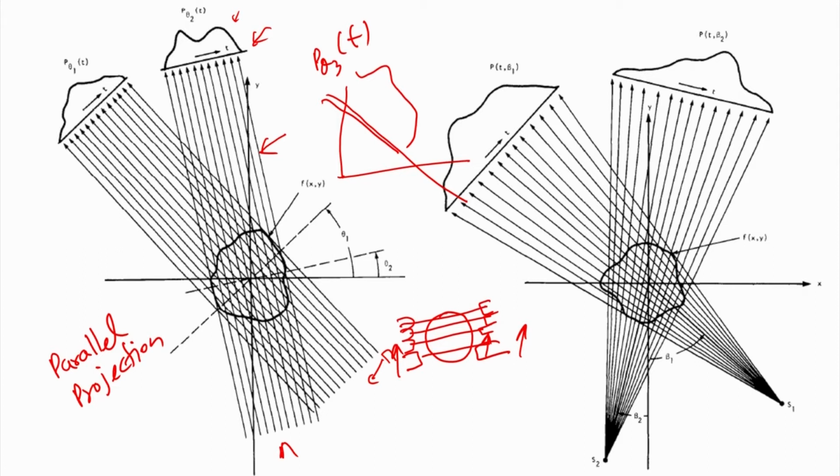So, what we do, we get this way and then we change it with the theta. The procedure remains the same, the post procedure remains the same, you get a projection. Now, you again move it at an angle theta, you get another projection, you do the Radon transform for each projection, then you take the FFT, and if there is any filtering requirement, if there is any noise, you do it in the frequency domain, then you solve this and then you do the inverse FFT to get the pixel wise information. So, that is the procedure being used and we follow this method for the parallel beam and cone beam to get the pixel wise information.